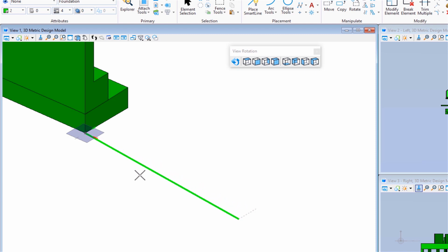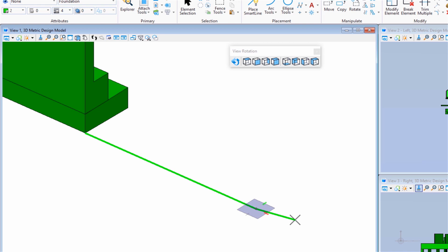If I move it away, I'm still constrained at 5, but you can see there's dotted lines right here. As I move it out here, I'm indexed on this axis. Now I've constrained the distance. I'm just going to do a data to accept it. The compass goes to the other end.